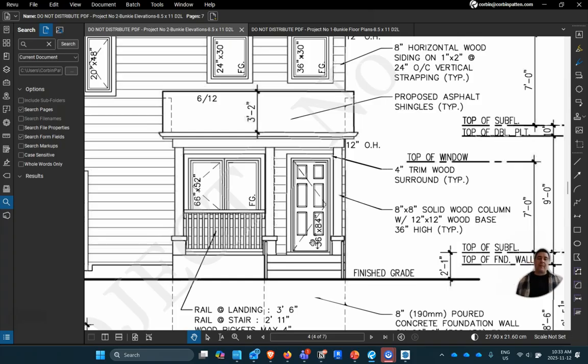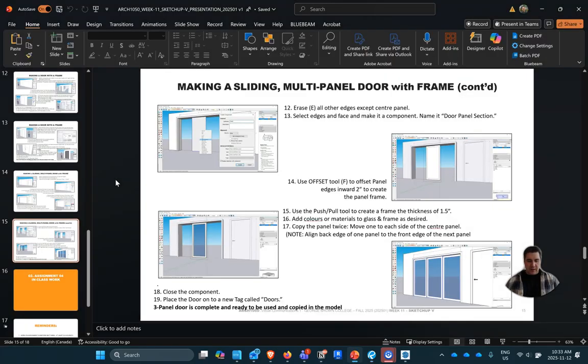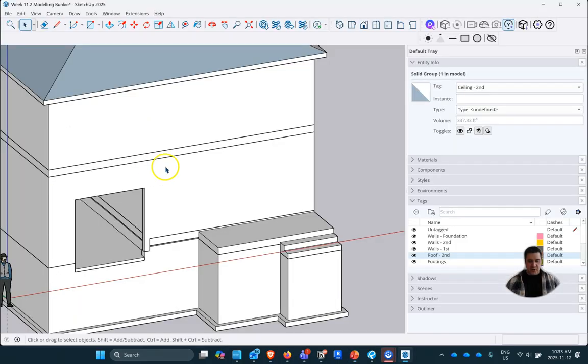And so I'm going to assume, just because I don't have any information, there's roughly 1 foot between the top of the door and this beam. So I don't have a dimension for that. I'm just going to assume that. And then the other thing we have here is our 6x12. So let's start off by modeling our beam. And so let's go back to SketchUp.